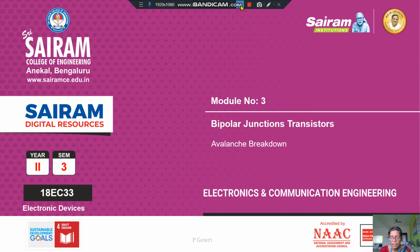Punch through is a phenomenon at which the depletion region extends throughout the metallurgical region of the base, and hence the depletion region will touch the emitter region. The holes in a PNP transistor which emerge from the emitter region will be directly diffused to the collector. Because of that, the transistor operation is lost. So punch through is one type of breakdown mechanism which happens in a transistor.